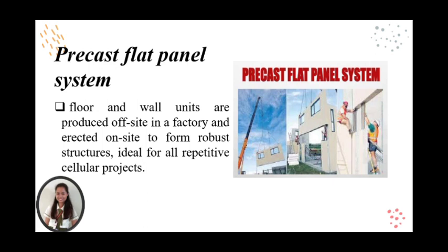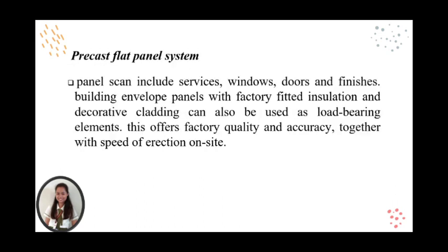The first method is the precast flat panel system. It is a construction technique that provides an alternative to traditional site-based construction. Precast flat panel system components are mass-produced off-site, making them practical for recurring requirements that also demand speed of manufacturing and consistency of product. Panels can include elements such as doors, windows, and floor units.